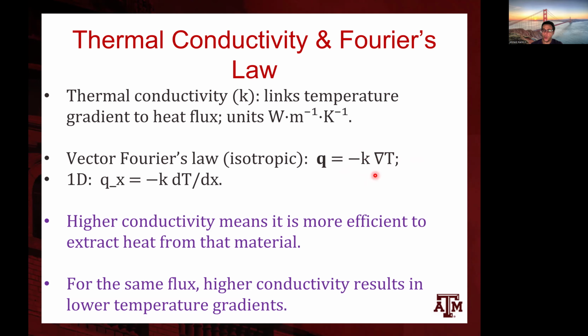And this is a very common form in constitutive or material laws. It has to do with the fact that those are the simplest forms of constitutive laws that we can introduce that don't violate the second law of thermodynamics. So the simple 1D version of that in a Cartesian geometry would be that the x component of the flux vector is proportional to the first derivative of temperature in the x direction.